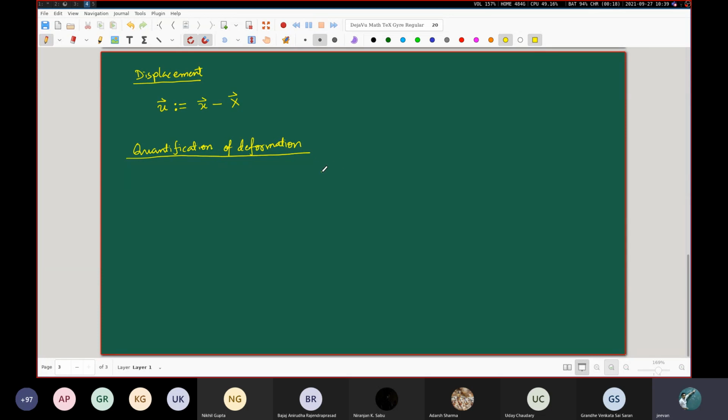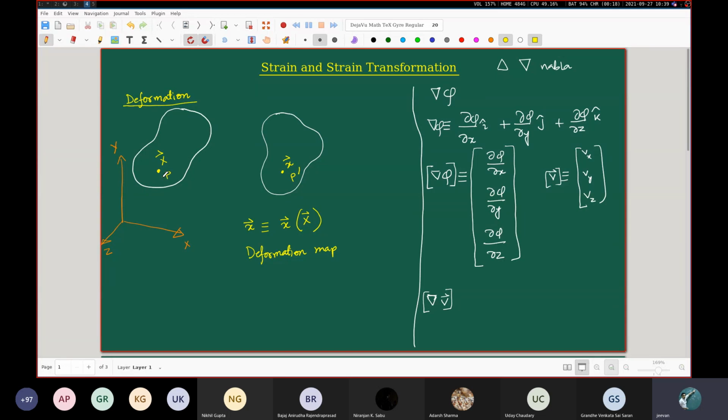You see, previously when we were talking about this kind of a deformation, we were tracking basically just a single material point as it goes from here to here. When you track this, of course, you are getting the entire displacement field through your definition of u, but it does not give you a direct, visual kind of understanding of how different points located within this three-dimensional body change their relative distance. What I mean to say is that if you just concentrate on this point, this point remains as a point here also. If you just look at that one point, sure you have all the information embedded in the displacement vector, but it doesn't give you a proper understanding or visual representation of how this overall shape has changed.